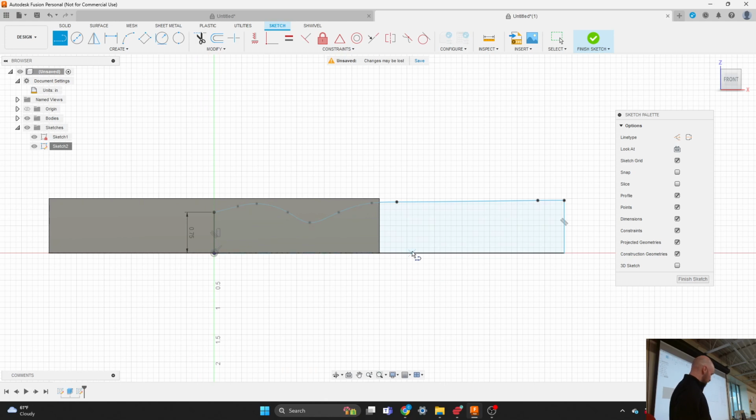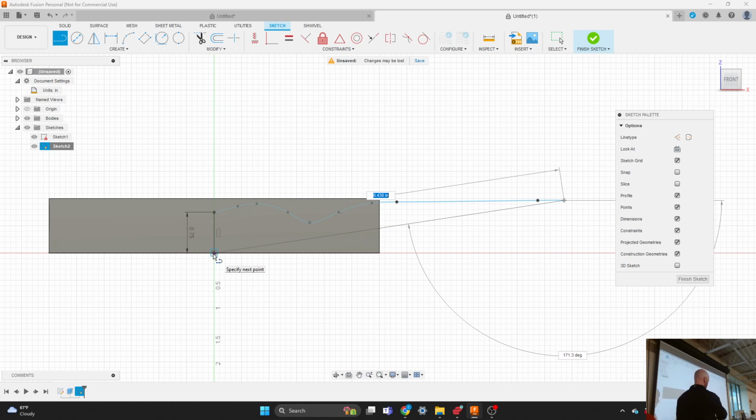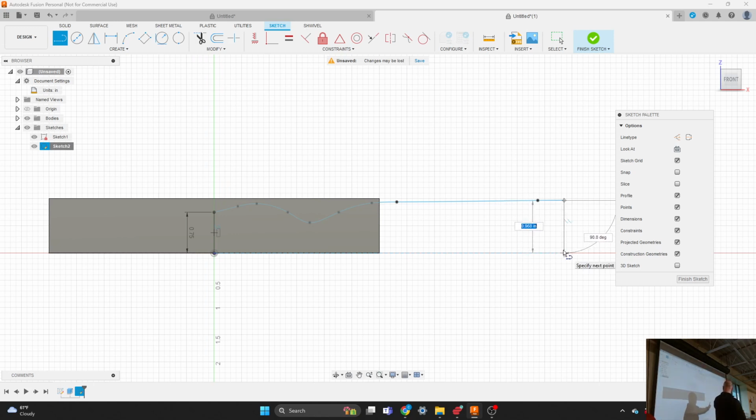And there we go. How'd you go from your curved line to your flat, straight line there? A trick that I like to do is, if I know I want to draw a line, we can do it two ways. One way is, if I hover my mouse over my origin point and slowly move my mouse off to the right, there's a little blue line that pops up, saying you're trying to make these things horizontal or vertical from each other. I can click and place that, and it's going to be strictly right across the way.